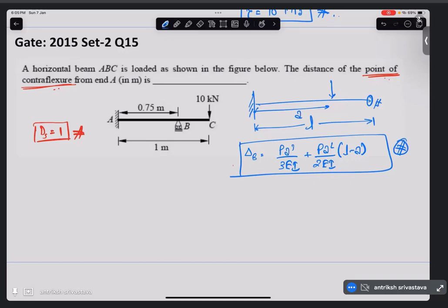But this is to extrapolate, because the curvature of the beam looks something like this till the load is applied, not linear, and after the point of load application it becomes linear. So we just multiply with the slope, what is the value of this distance, and we added this part to this main deflection. So that was an easy question, but in this question we cannot use this formula because we have to identify the deflection at a point that is ahead of this beam.